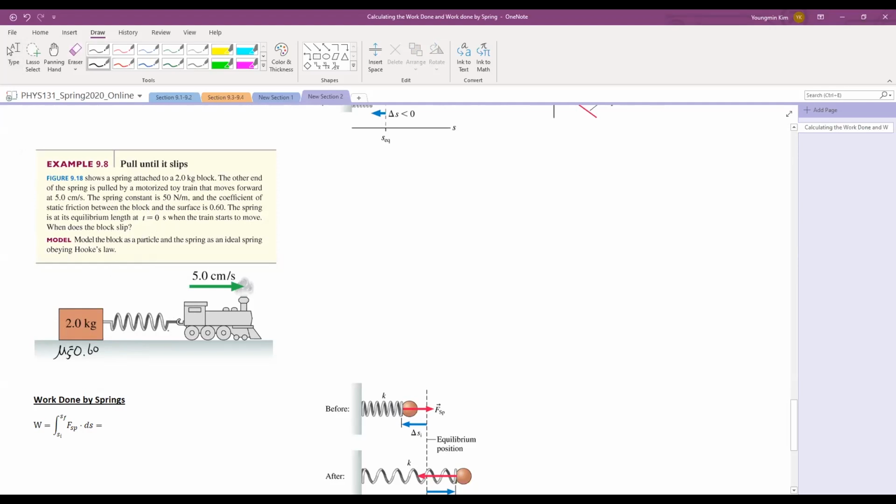First of all, when dealing with forces, it's always useful to draw a free body diagram. So consider this from the box's perspective. We have the force of gravity pulling it down, and the normal force pushing it up. Now think about this spring.